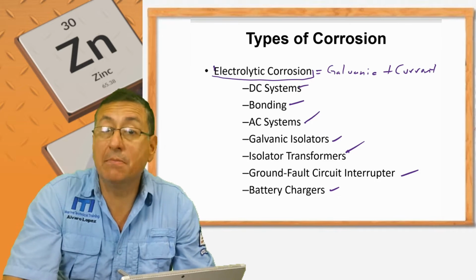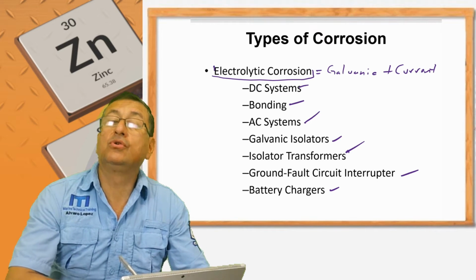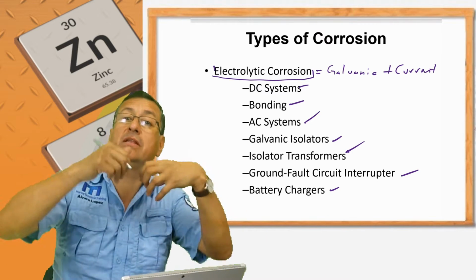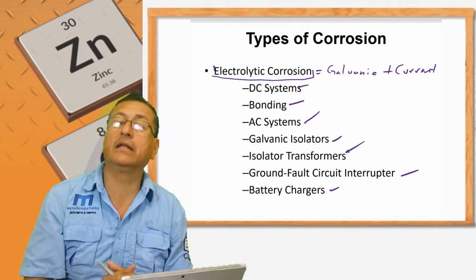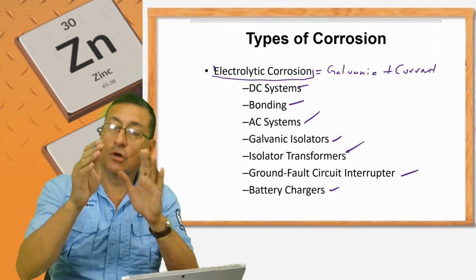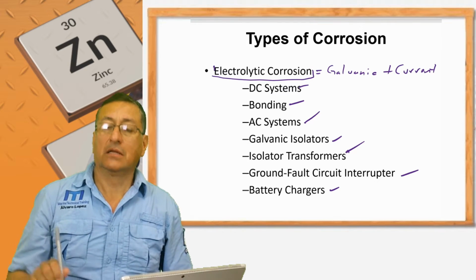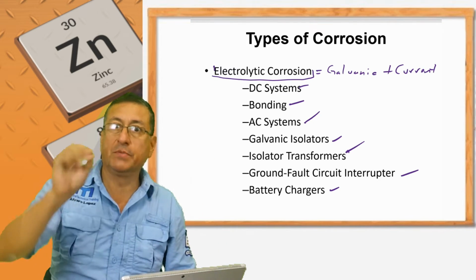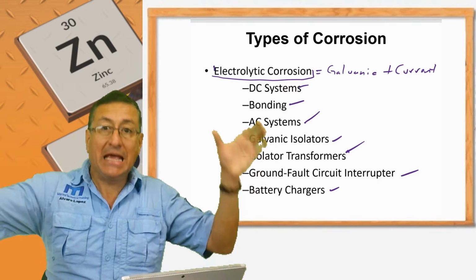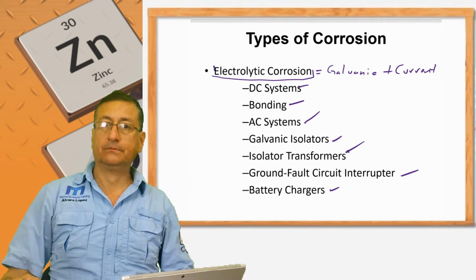Use marine battery chargers and marine inverters, because those equipments are isolated from the beginning inside and are designed for marine environments. If those elements, battery chargers and inverters, are metallic, the case of those elements should be connected to the AC ground bus bar. AC ground bus bar, ABYC question.